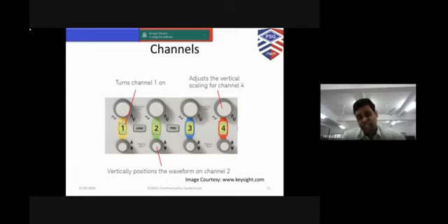So if you have a 4 channel MSO in your laboratory, we can measure 4 signals parallelly, and those 4 channels have to be selected. We have a visual display for that, and these lights will glow at 1, 2, 3, 4. If a light glows, it means that channel 1 is on, 2 is on, 3 on, 4 on, depending upon it.